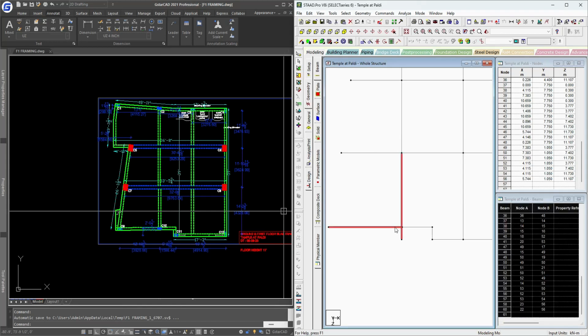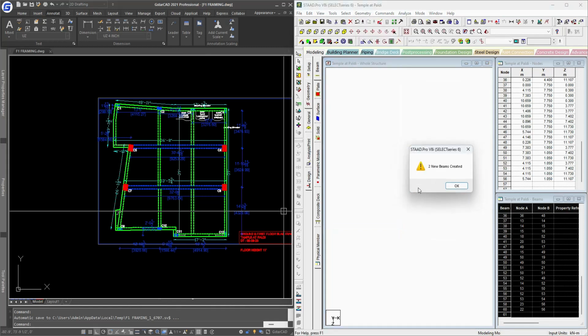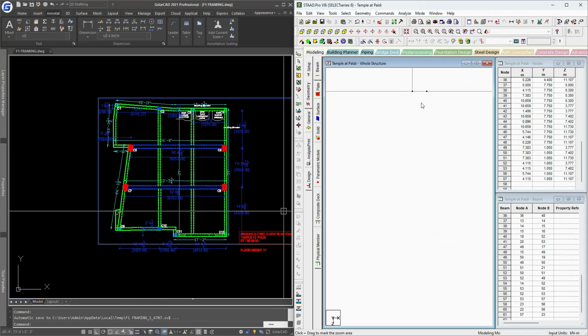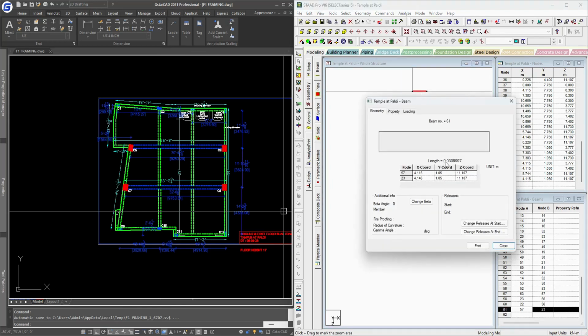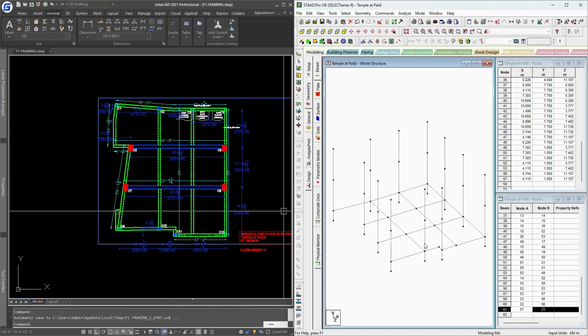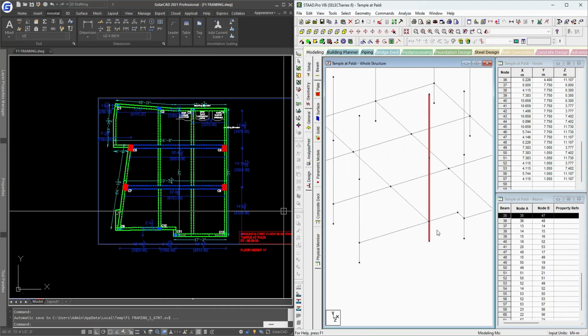So first let us select these two beams, go to geometry and intersect the beams, so that you can get the intersection point where these beams are being connected. As you can see, it's a very small distance. Selecting it, it will show it is just 31 mm. The ideal condition I'm doing is I'm just shifting my column to that point.